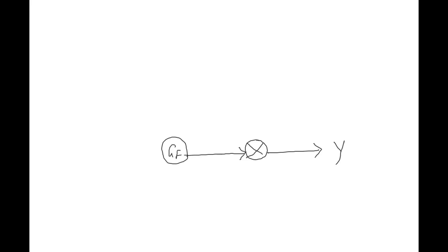See, this is a slightly different loop. So this y is my response. In the previous one, you have to follow as it is. There, this is slightly difficult to understand, so I'm trying to explain it slowly. Level is my response. Your level gets affected by two points. One is your final control element opening. If you open the valve more, the level will go down. If you open the valve a little slowly, then the level will go up.